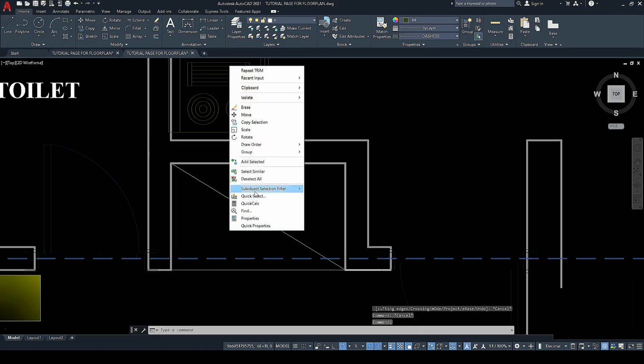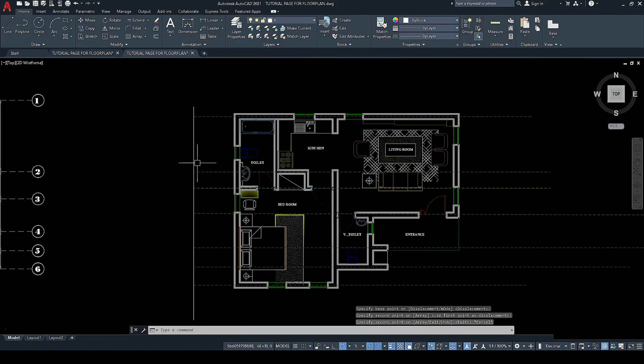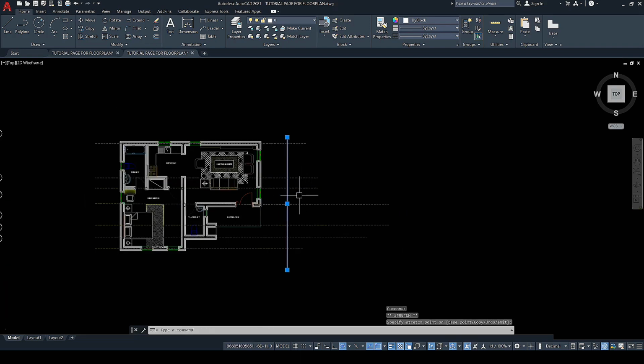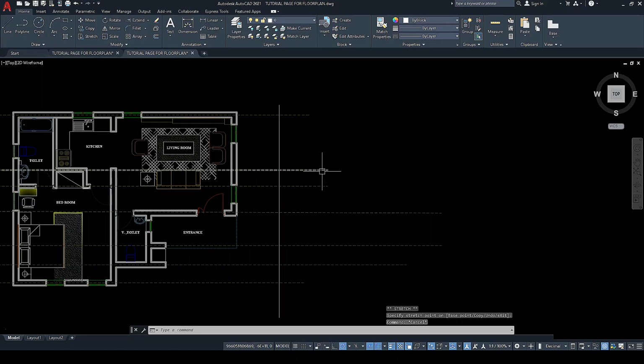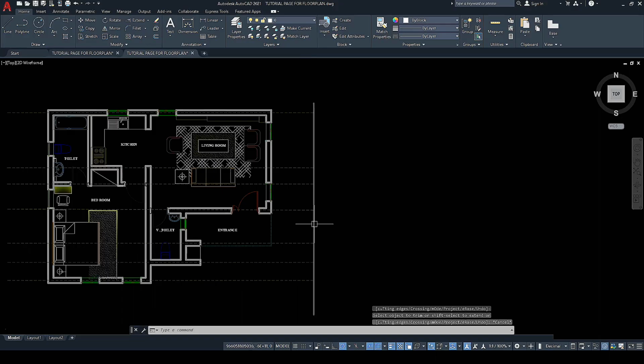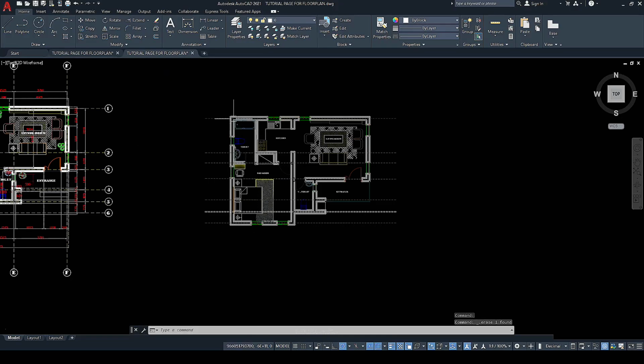So we'll transfer, okay, the remaining. We'll do the same thing. We'll copy this at this point and bring it up here. So we'll transfer our vertical guide for our grid boundary to this position, our east polar region. So we can pick our trim tool, then we trim off all of these excess lines. So we've succeeded in creating our horizontal grid.